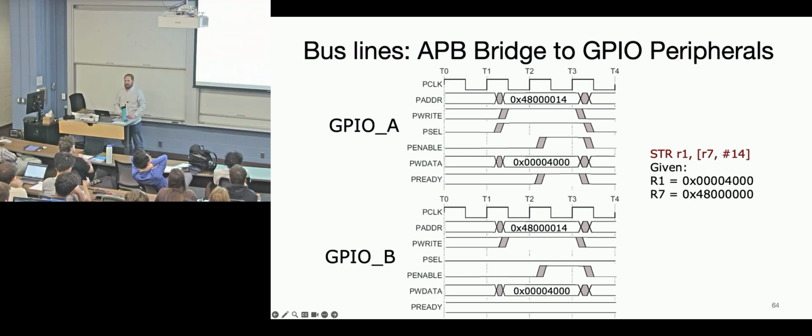So are you kind of saying like after the action happens, it's not that important when it goes back down? I am saying it doesn't ever have to go down, and in this particular example, this drawing is showing that it doesn't care if it's high or low. It happens to be high, and so there's some peripherals that are always high. Like if it's just a register, it will be done in one clock cycle. It does not matter, it's just high. But if it has to wait, it will be pulled low. And then when it rises, that's the indication that on the next clock cycle it will be ready.